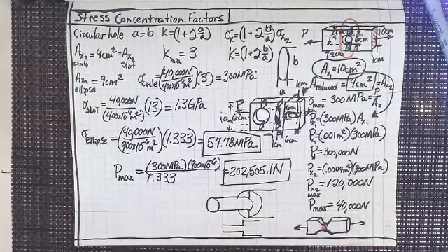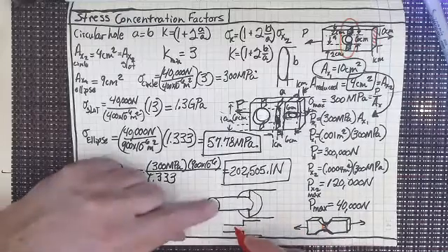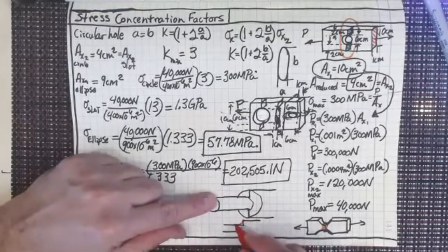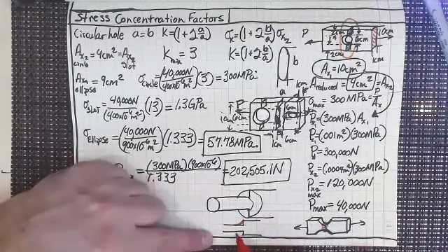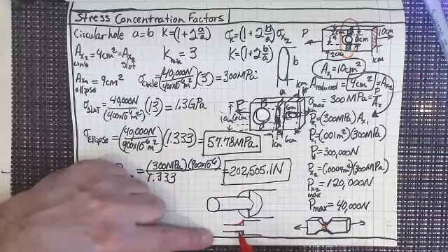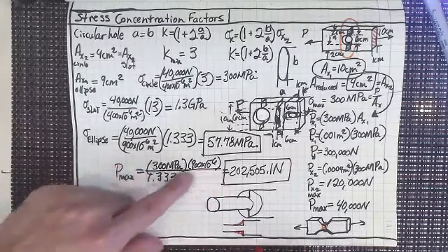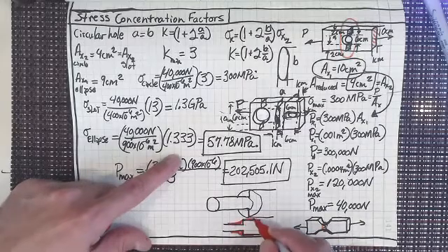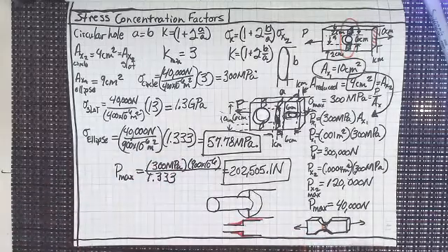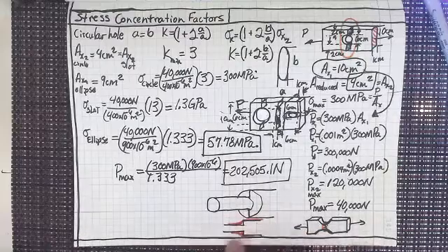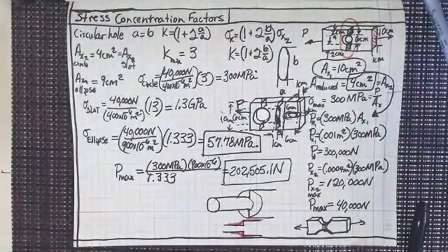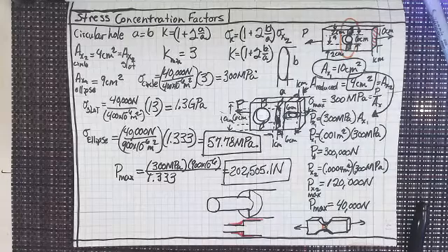So what you want to do is you immediately want to fillet these out. And how do you want to fillet them? Right? On a semicircle, don't you? To minimize that thing. So you'll go like that, right? That's how you want everything to be smooth. No jagged edges on any of the things that you're doing, or that just adds an infinite stress concentration factor.